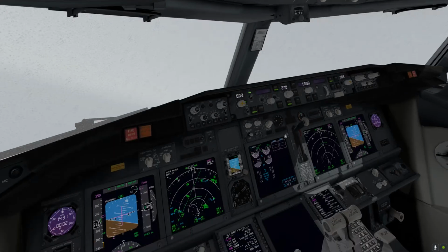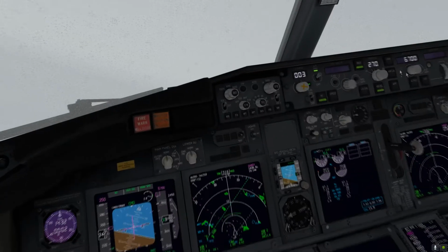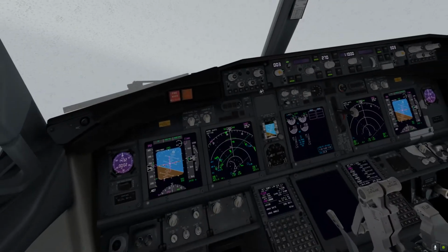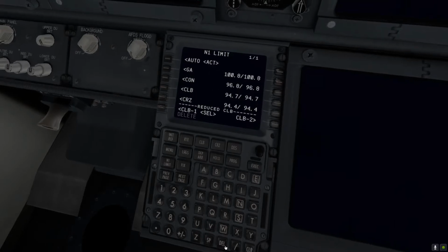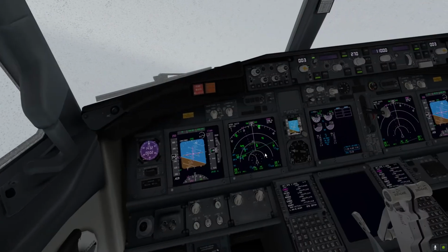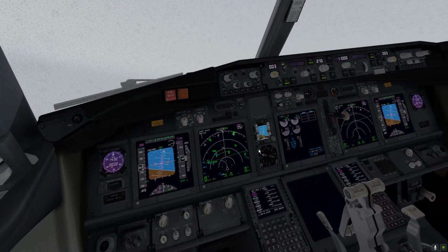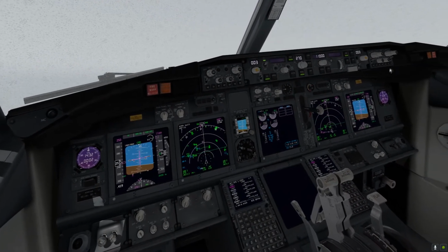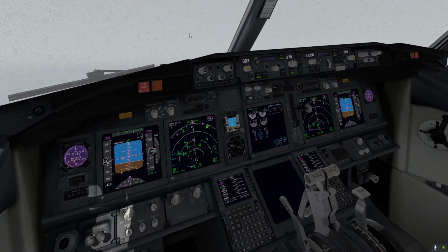This is still first officer flow. Perfect. Let's climb a little bit more. Assuming 1000. And now we set also down here a full climb thrust. We want full climb to go up without restrictions. This seems pretty good to me. Temperature is nice, still well above conditions of ice. So this sounds pretty good. Very nice climb out.